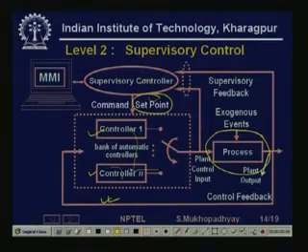So it gives set point, but it does another very important thing, that is, it is not always that you are going to use the same controller. For example, the controller that you may be using during the time that a plant is started up from, let us say, cold condition, or when a plant is shut down, they are actually totally different control laws. So, you may have more than one control law. If you are doing startup, you use this controller. If you are doing shutdown, you use another controller. When you are doing normal operation, you use another controller. So, you must give commands as to which controller to use when.